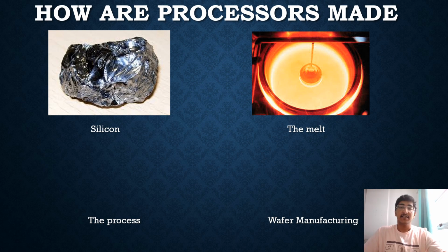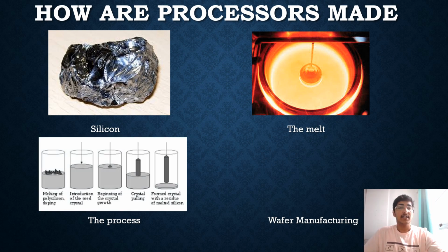Now after it reaches a certain temperature, we slowly lower an ingot into the melt and cool it. As the melt is cooled, crystallization begins to happen on the surface of the ingot. What this ingot actually is, is just a cylindrical circular deposit that's lowered into it upon which crystallization takes place. Now after it's cooled, the ingot is slowly taken out, rotating it. The rotation is done so that any temperature irregularities can be corrected, and it's basically bullet shaped, right?